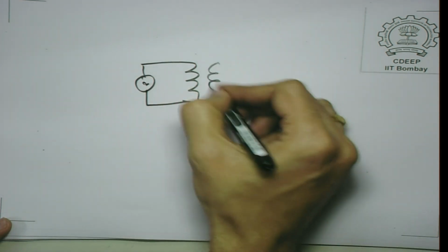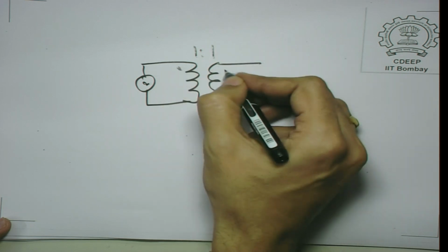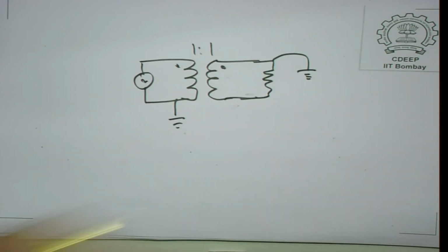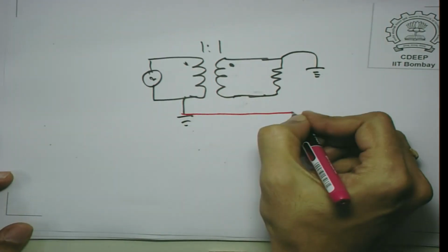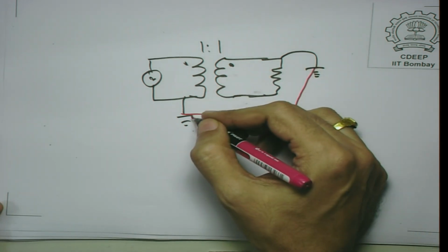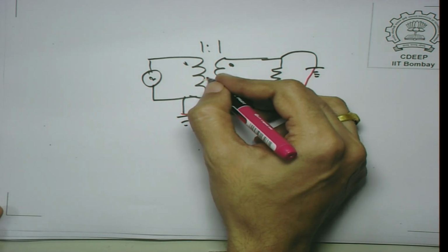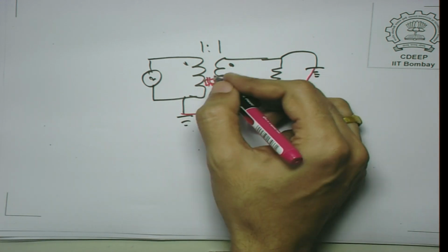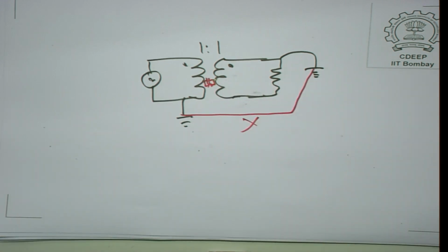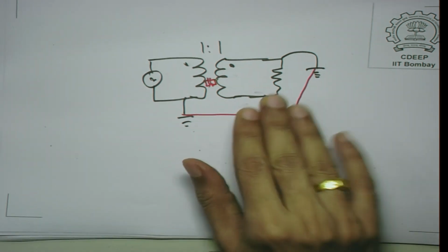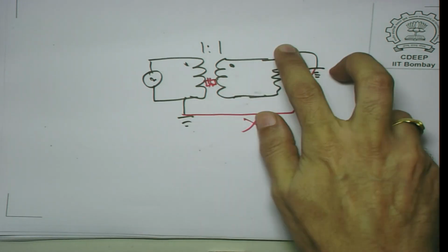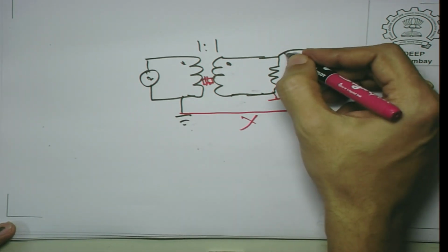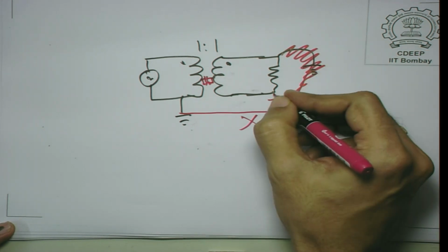If you have got a transformer, the same circuit, let us take a 1:1 transformer, I have got a resistance and I can actually ground this point and I can also ground this point. Now, this is effectively connecting this point to this point, but does it affect the circuit? The answer is no, there is no return path for this current. What will happen is of course, there is a kind of impedance in this path because of the insulation resistance as well as the capacitance between these turns, but this is an extremely high impedance. So, for all practical purposes hardly any current flows through this. Because no current flows through this, for all practical purposes having this connected here will not affect the original circuit. So, if you connect the ground here it does not matter, you can connect the ground here also. Well, you can't connect it both at the same time, but if, for example, I remove this and connect this to ground, this also will not affect the circuit.